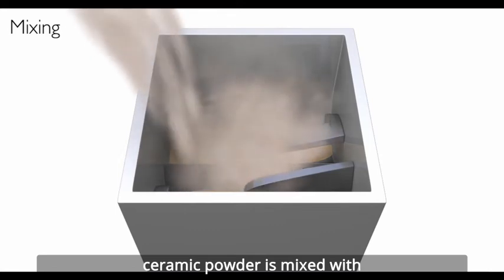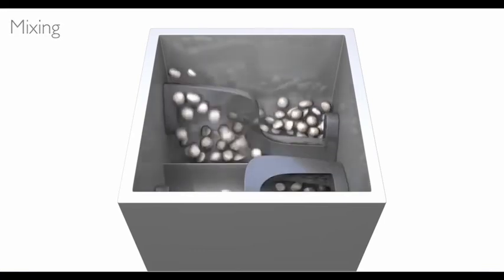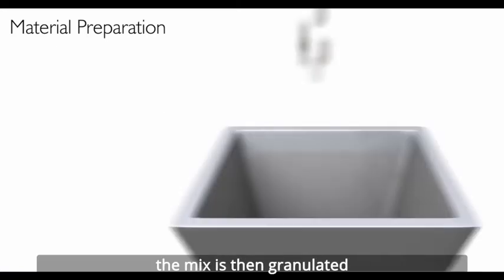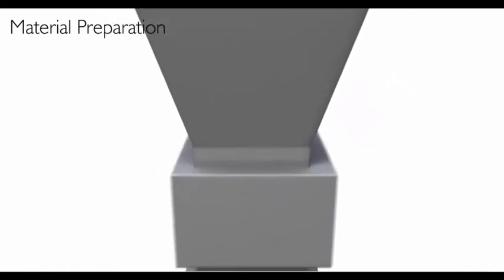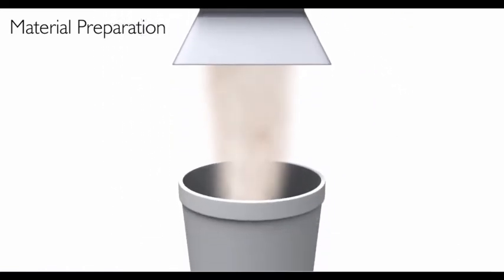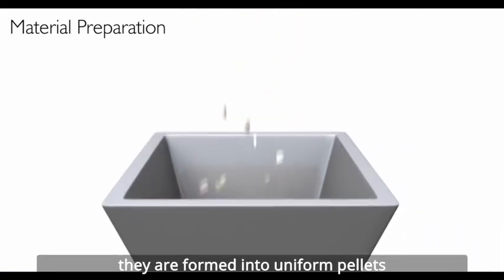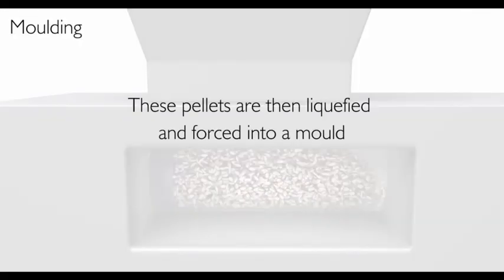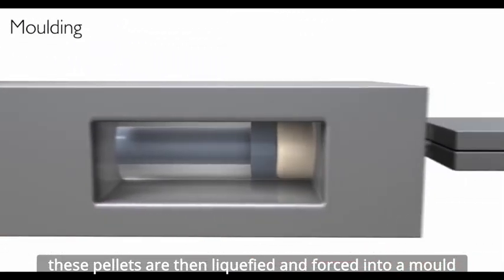Ceramic powder is mixed with a thermoplastic plasticizer and other additives. The mixture is then granulated. They are formed into uniform pellets. These pellets are then liquefied and forced into a mold.